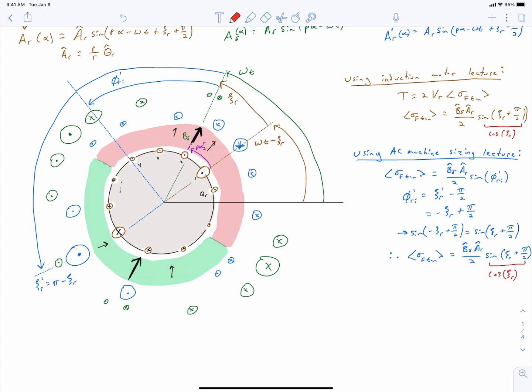So this is satisfying. This shows us that our laws of physics are being followed. We can study the stator current densities alone and end up getting the correct torque on our machine, or we could study the rotor current density with the magnetizing field and also get the same torque on our machine.